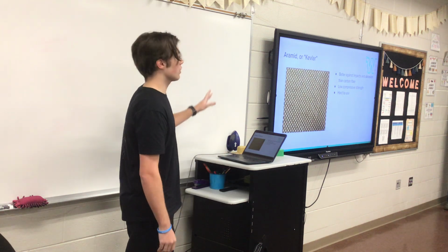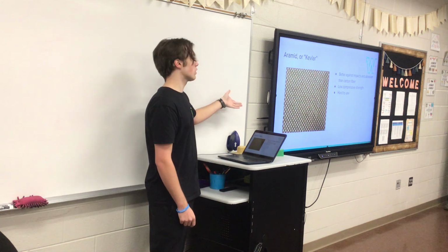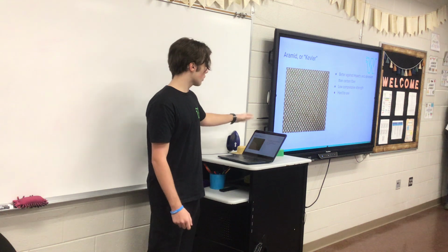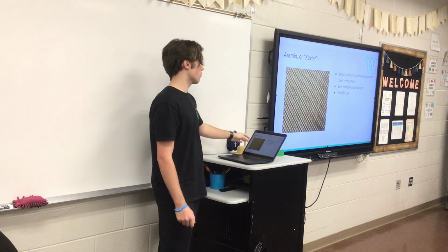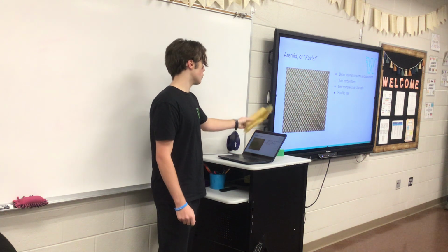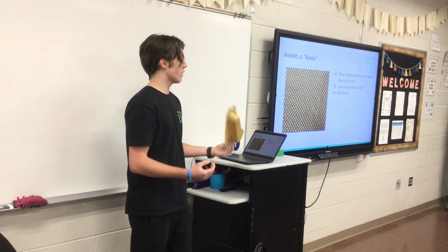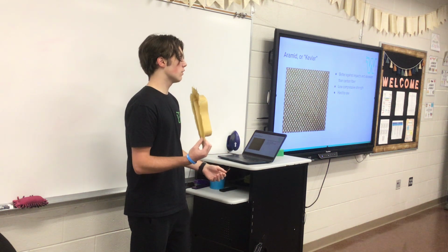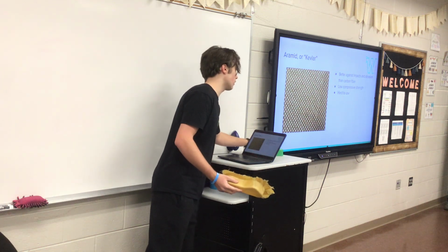So I'm just going to go through the types of fibers that can be used. First off, aramid fibers, otherwise known as Kevlar. They have really strong resistance against impact and abrasion, and a low compressive strength. However, it's very hard to machine and work with. This is a piece my team made recently as a demo piece out of Kevlar. Having worked on it, I can tell you it was very hard to machine it into the shapes we needed to get it to form around this 3D printed mold.